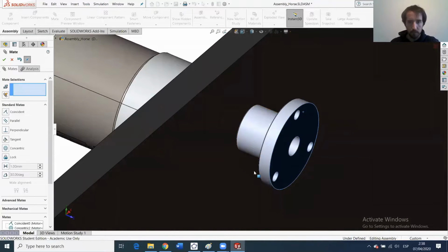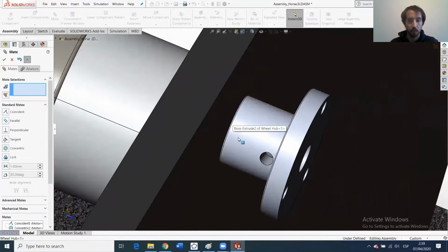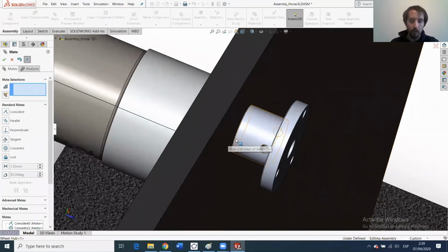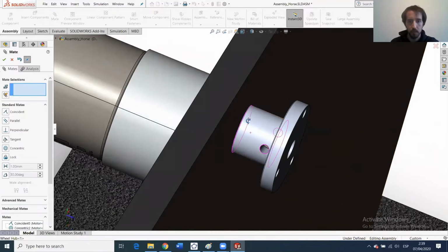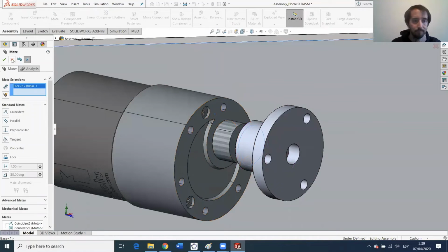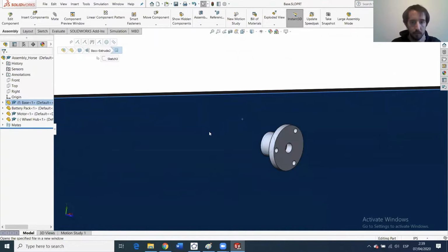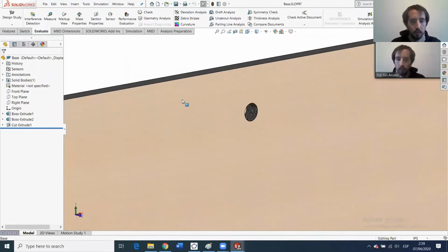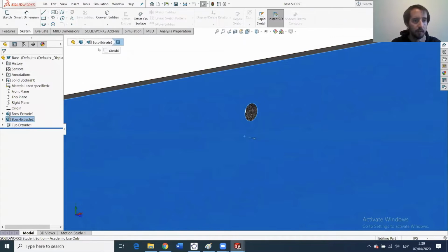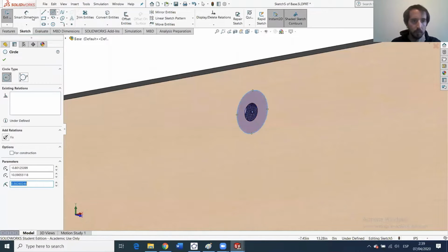You will see that this will be rotating, right? So right now, this surface and this object are not colliding. However, in reality, the distance will be so close that we could have problems. So if we want to be strict, what we have to do is go here, open it, and then sketch another hole which is bigger, just to avoid problems with friction.